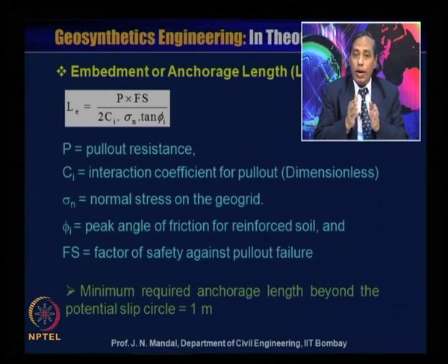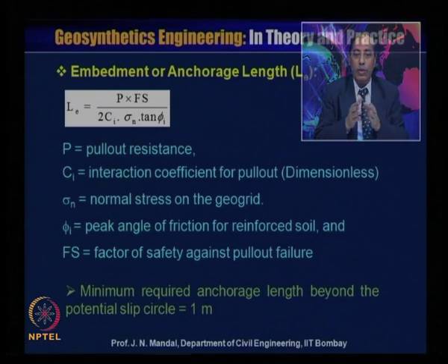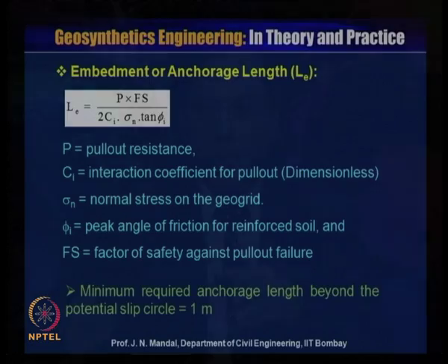So, the minimum required anchor length behind the potential slip circle should be 1 meter. If it is less than 1 meter, then at least you should consider it to be 1 meter.